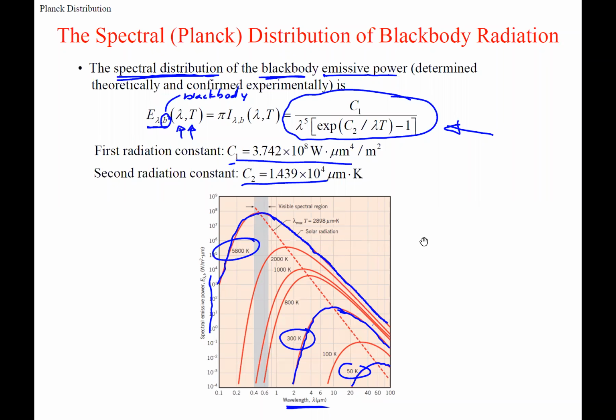This is a very important figure because it tells you, depending upon temperature, say your table, or if we're solving for the surface temperature of something, as we did a lot even in chapter 1, whether that surface is going to have a lot of emission at high wavelengths or low wavelengths.